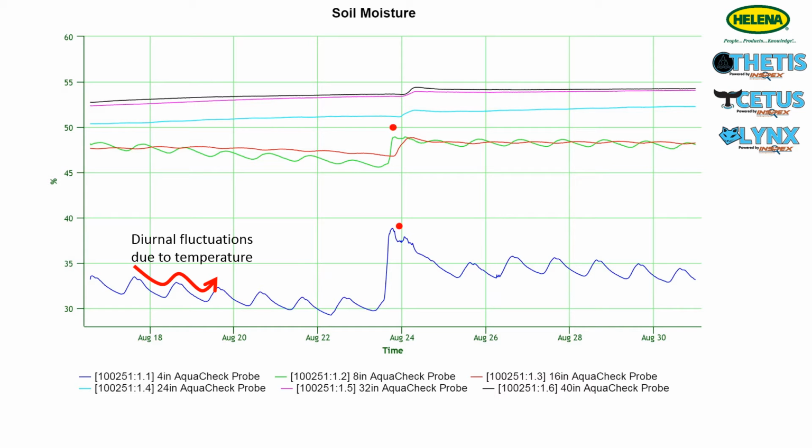This sharp increase in relative soil moisture signifies an irrigation or precipitation event. If moisture advances to the deeper depths, you will also observe an increase, but the relative change tends to be less because soil moisture distributes more slowly during unsaturated flow. Following the end of an irrigation event, there is a period of free drainage where the saturated surface soil returns to an unsaturated condition.